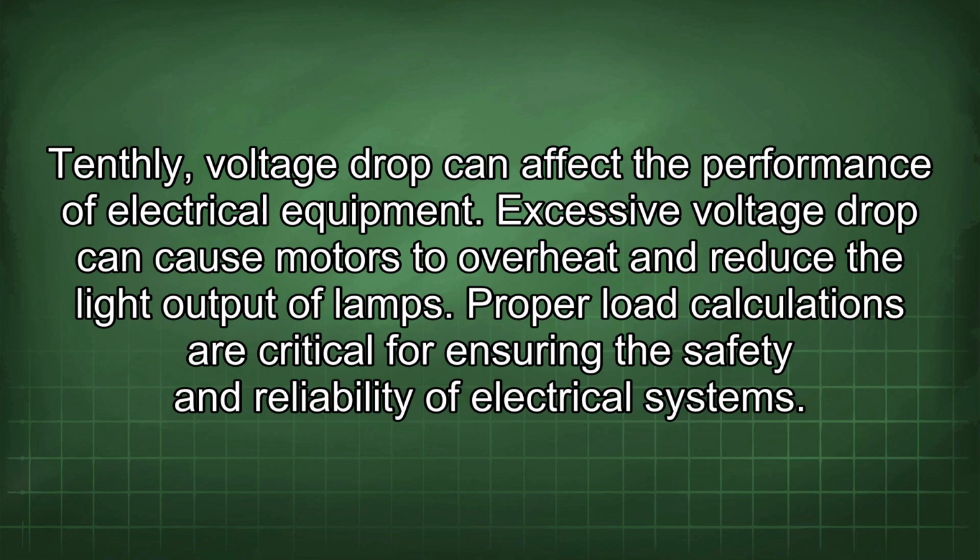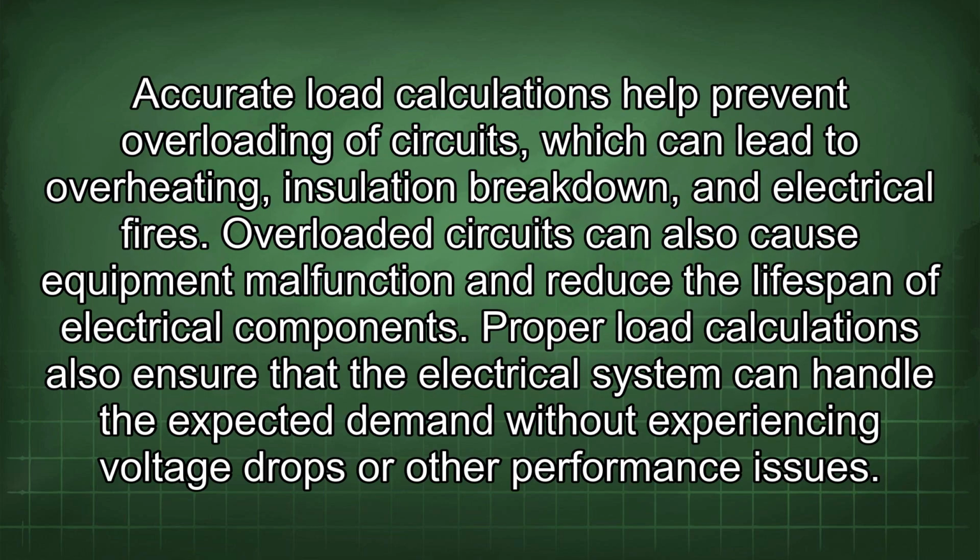Proper load calculations are critical for ensuring the safety and reliability of electrical systems. Accurate load calculations help prevent overloading of circuits, which can lead to overheating, insulation breakdown, and electrical fires. Overloaded circuits can also cause equipment malfunction and reduce the lifespan of electrical components. Proper load calculations also ensure that the electrical system can handle the expected demand without experiencing voltage drops or other performance issues.